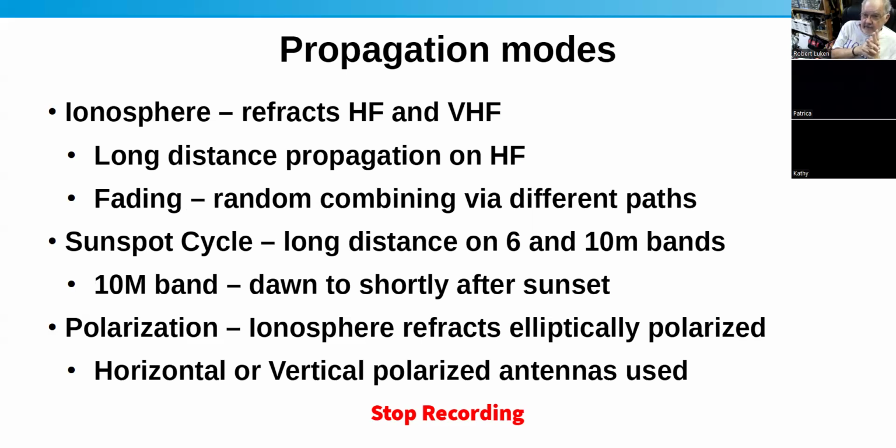You may get something called fading because those refractions are taking possibly different paths, and they don't all get to the receiver at the same time, like the multipath we talked about earlier. You can have that same sort of effect because the surface of these layers in the ionosphere is not smooth, and it is moving and varying. So you can get this fading effect because of that.